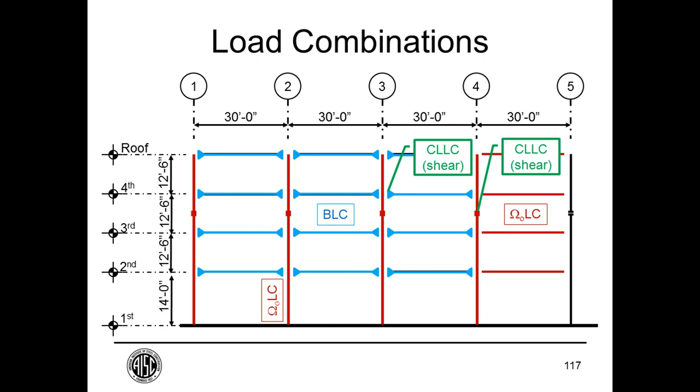So the question was the base plate, the anchor rods, and I'm sorry, what else? And the foundation was the third one. And the foundation, specifically mentioned. Yeah, so the foundation is not required to be designed for those amplified loads, but the base plate and anchor rods are. So you have to use a bit of judgment in proportioning those base plate connections.